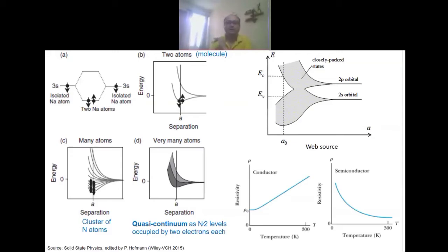But whenever you are taking silicon bonding, both have 1.8. If you subtract the two electronegativities, 1.8 minus 1.8 equals 0. Since it lies within 0.0 to 0.3, it's non-polar. That means silicon in this case is in a non-polar covalent state. But in the case of gallium arsenide, it is still a semiconductor, but it behaves like a polar covalent semiconductor. So this is the way we can classify different semiconductors.